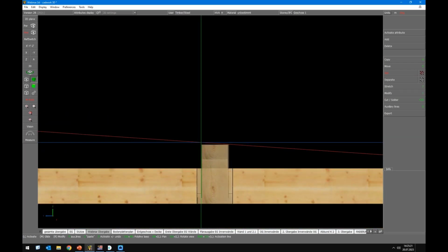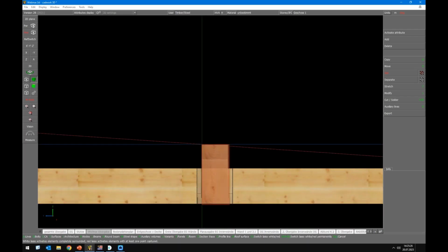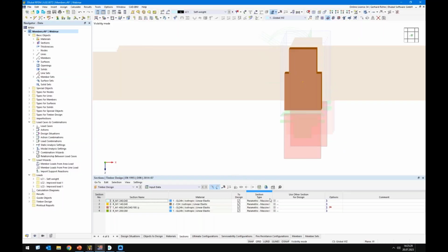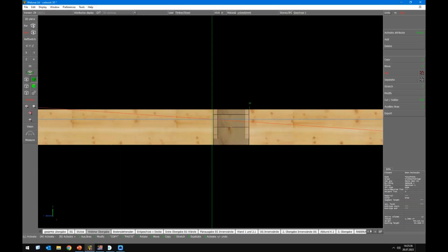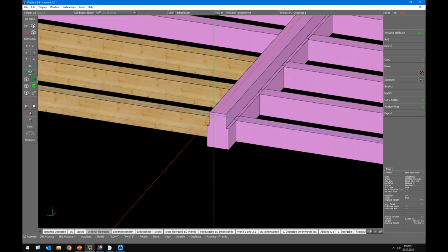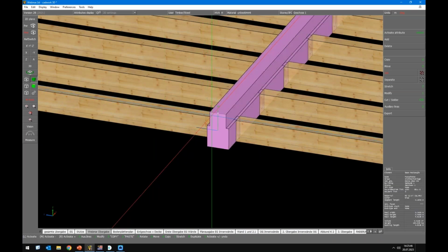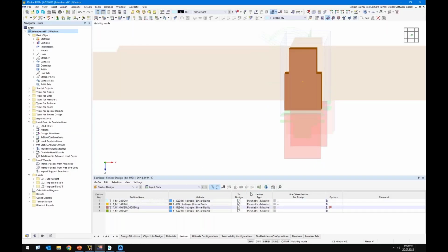which is here 180 by 400. So this is from this to this edge. And this we can directly use by using the option use other section for design. So for the left side, it was this one, 240 by 240. And this one is, I guess, 180 millimeter on the top side. Yeah, it doesn't matter. I guess it's the case. Yeah, 180. Okay, so we click here and then we will replace the width 240 with 290.